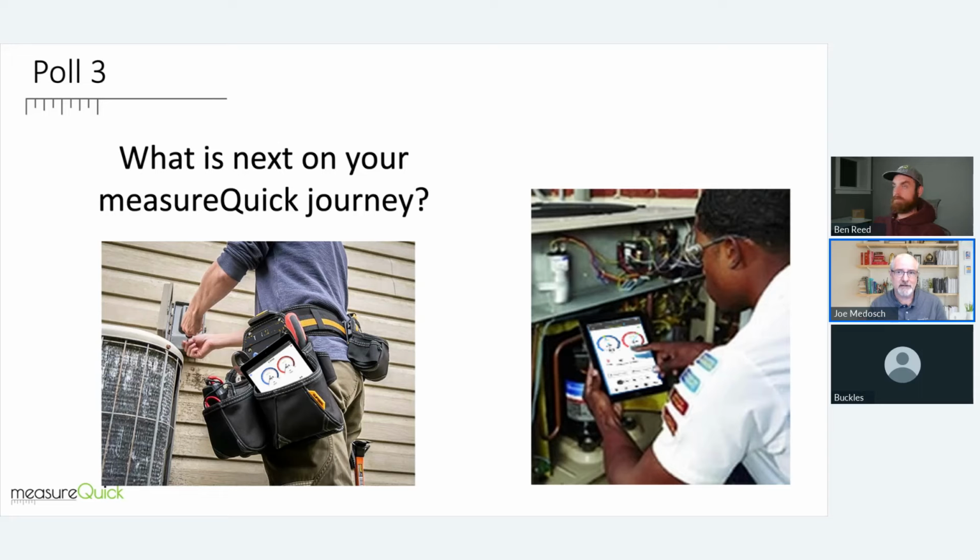Jim and I debate this. I don't take a system that's not doing well and benchmark it, because when somebody comes behind me, those benchmarks are now the criteria for determining whether it's working well. Somebody else may have serviced it, or something else may have changed, so I only benchmark something when I know that the system is at the best possible that it could be operating at that time.